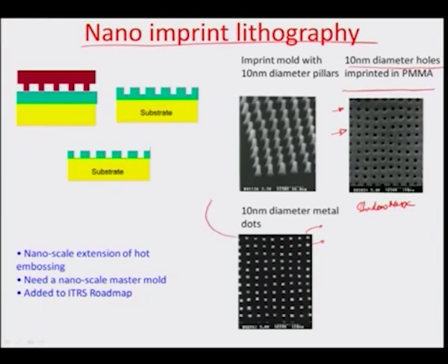So, you can actually make a patterning of these 10 nanometer diameter pillars with these dots shadow deposited on the top of this silicon using this PMMA. So, the power of the electron beam is translated in terms of resolution of these dots, which is further translated in terms of the formation of these nano pillars at a scale which is very small and minuscule.